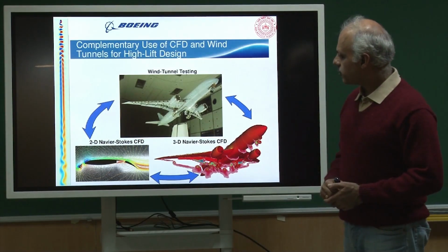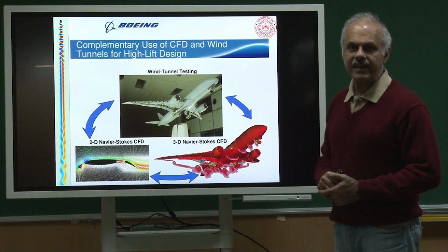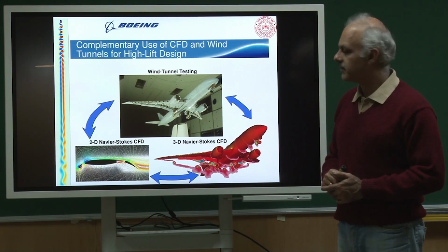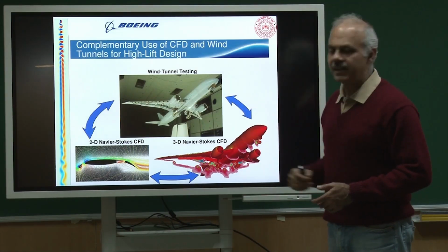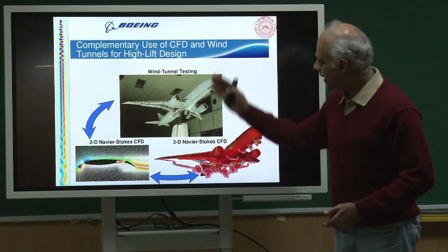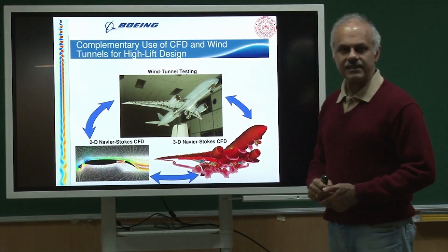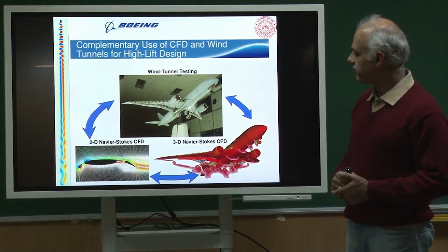What you can also do is that maybe these 3-dimensional high fidelity models are very expensive, they have a very large turnaround time. And let us say I was only interested in designing the flaps and the slats of the aircraft for the time being. So, I could take a 2D section of this wing, for example. So, that is my airfoil section. I have a slat and then I have a flap downstream of it.